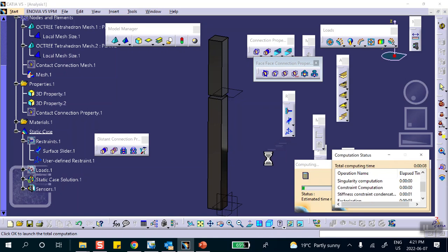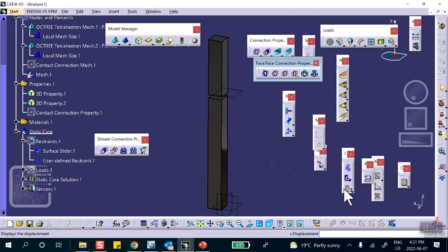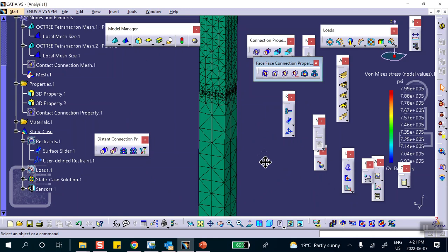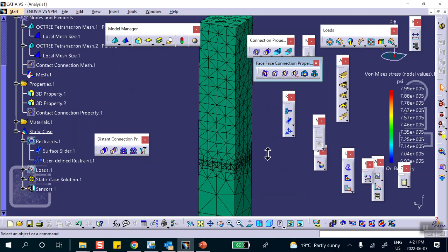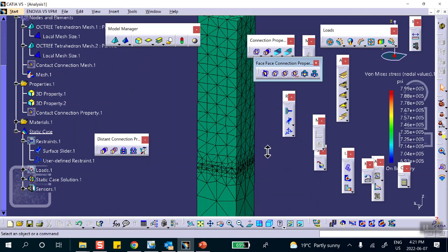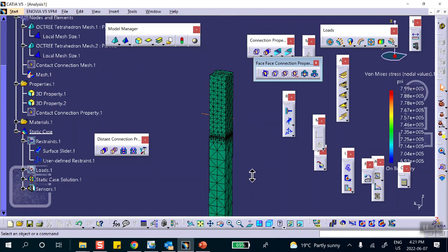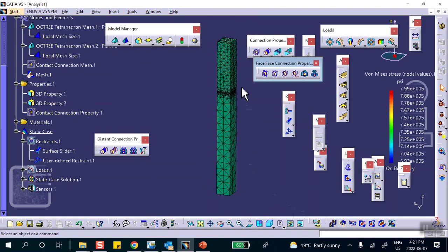The name suggests what it means. In other words, the two faces get as if they were glued together, and if you look at it, yeah, no sliding. They get stuck, and essentially, when they get stuck, it becomes one piece. Okay, becomes one piece, and that's why the stress is the same everywhere. Okay. So no sliding means that once the two pieces reach each other, they get glued, tied, or they don't slide on top of each other.